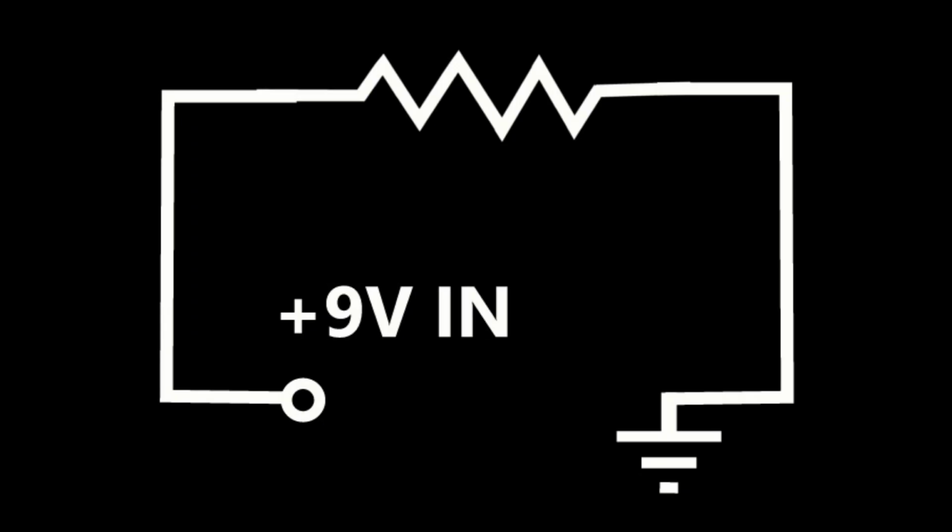It is possible to measure the voltage of a circuit without changing the circuit. The voltage potential is simply measured across the positive and negative sides of the circuit. To measure amperage, the current through the circuit must be measured. This means one end of the circuit must be disconnected from the power source, and the measuring device must be connected in line with the circuit.